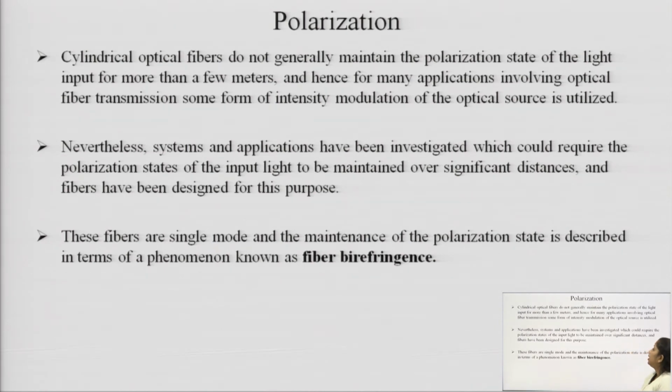Now, cylindrical optical fibers do not generally maintain the polarization state of the light input for more than a few meters. Cylindrical fiber does not maintain the polarization more than a few meters, and hence many problems arise. The major one is mentioned here.